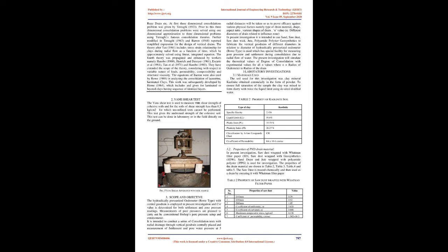Most of the soil deposits have greater permeability in the horizontal direction, which can be utilized efficiently by the use of prefabricated vertical drains. After the use of sand drains, several new types of geodrain have come on the horizon, with different shapes and materials, namely sandwick drain, jute drain, polypropylene drain, cardboard drain, rope drain, etc.